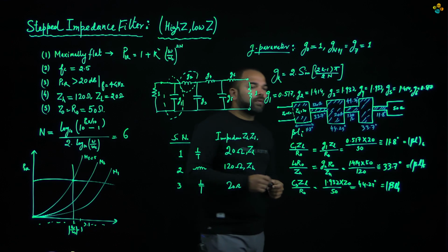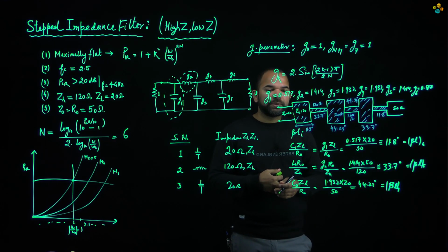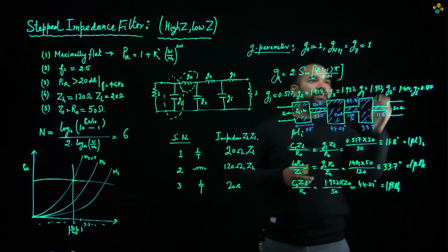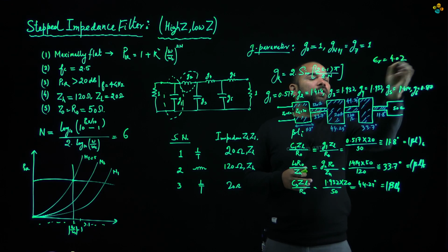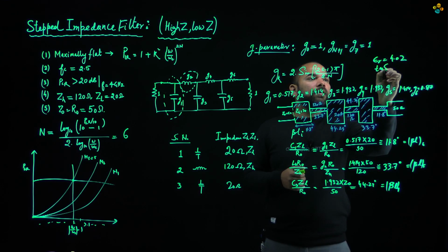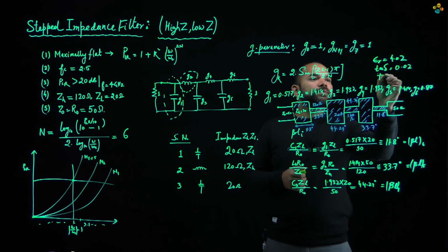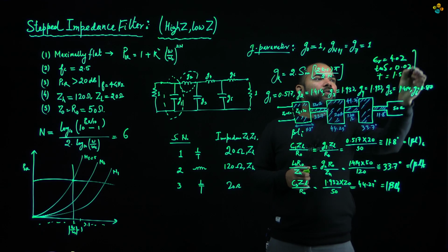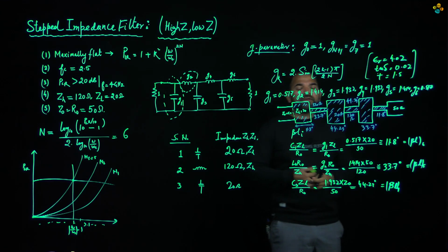And if we are given the parameters for the substrate, say suppose we choose a substrate to have a permittivity epsilon value of 4.4, and if the tan delta is given as 0.02 and the thickness of the substrate is given as 1.5, so we can practically realize these filters on a PCB technology.